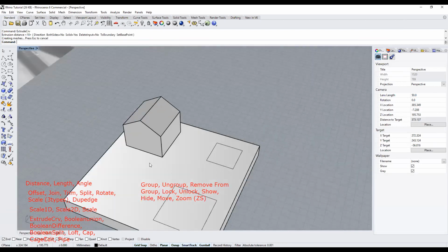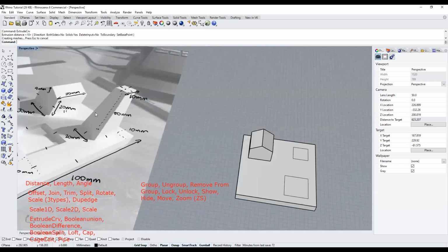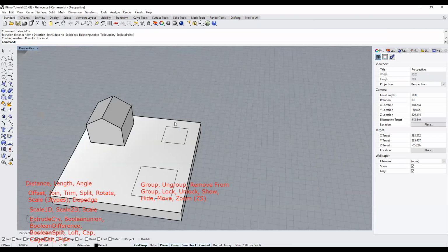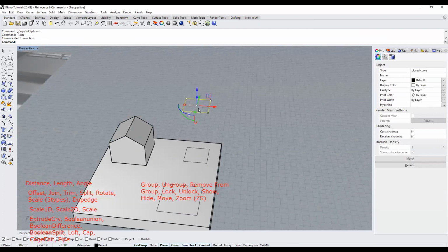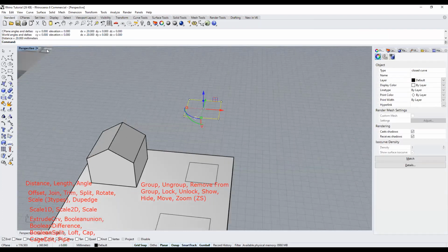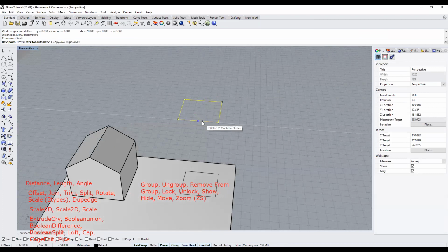As for the trapezoid, it is 50 millimeters off from the top. So I'm just gonna copy and paste this. Control C and Control V, move it up by 50 units. Right now the distance between each of these points is 20. So the top is 2 times smaller than the bottom. So I'm gonna scale this from the center point. I think that will be the easiest.